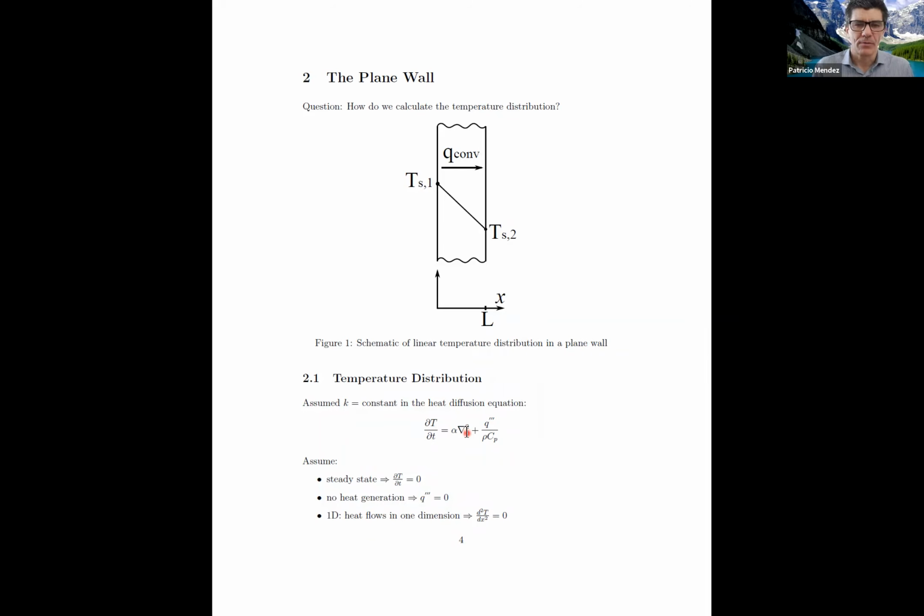But there's more, because in the X direction I have a gradient, but the Y and Z directions mark the plane of the wall. In the plane of the wall, if one side is at a constant temperature and the other side is at a constant temperature, the heat doesn't move sideways in the wall. That's why this is 1D heat transfer.